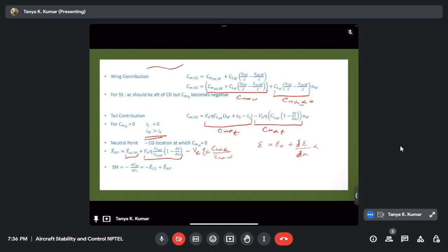So this is your aircraft, right? And you have a wing here, you have the tail here. The wing is longer than the tail. Okay. So now, imagine another view of the aircraft where the flow from below the surface of the wing interacts with the upper surface flow of air above the surface of the wing. At the point at which it interacts, both the velocities coincide and you have some vortices generated. Now these vortices travel downstream towards the tail. This effect is known as downwash.